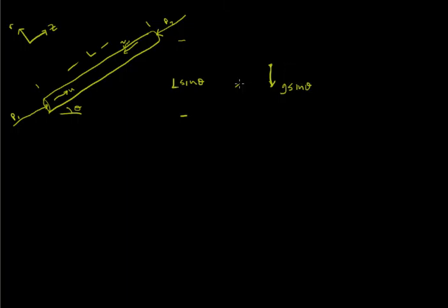And then we have a pressure acting up like that. It'll be P1 times the cross-sectional area. And we have pressure acting down. So that will be our P2 times the cross-sectional area. Then we have a shear stress acting in this direction. So that will be our tau sub W times the surface area. So this would be our force diagram.